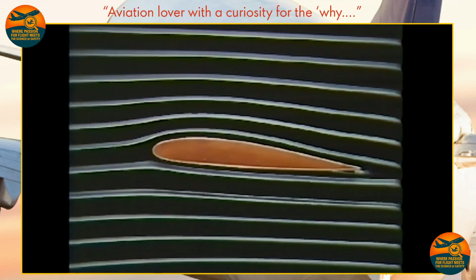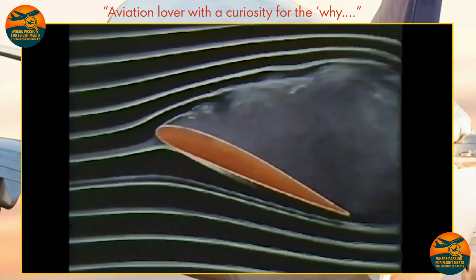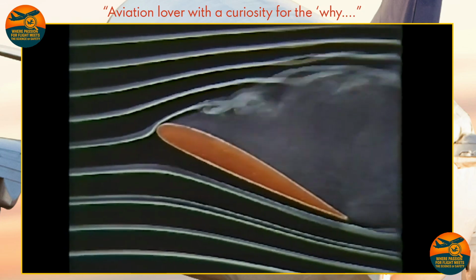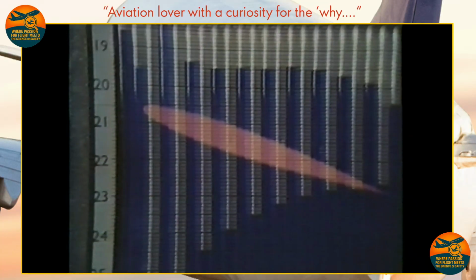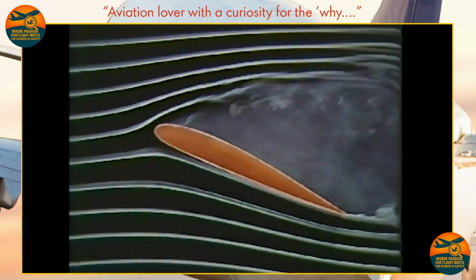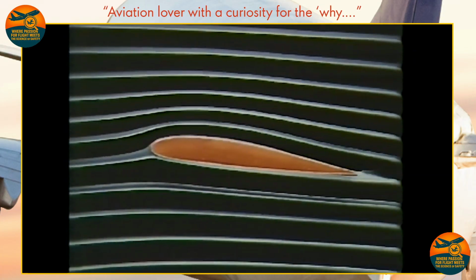But the extent to which we can increase the angle of attack to the relative airflow is strictly limited. If we increase the angle by more than a certain amount, depending on the type of aeroplane, this happens. The airflow breaks up over the upper surface of the wing, the pressure pattern becomes unstable, lift decreases sharply. The wing has stalled. This can happen at any speed once the wing has reached the critical angle. Thus we can see that the pressure difference that gives us lift can only be maintained if the airflow over the wing remains smooth and undisturbed.